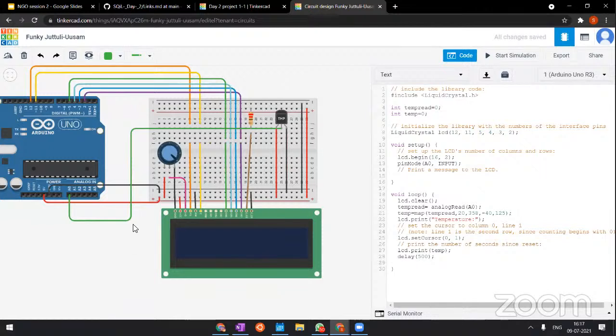Yeah, I assume you mean the data bits on the LCD screen. There are 8 pins, DB0 to DB7, not 9. There we can use all the bits, or we can use only 4 bits. 4 bits serves the purpose for us. There are 2 modes. We can use the 4-bit mode and it serves the purpose very well. We don't need to use the other 4 bits.